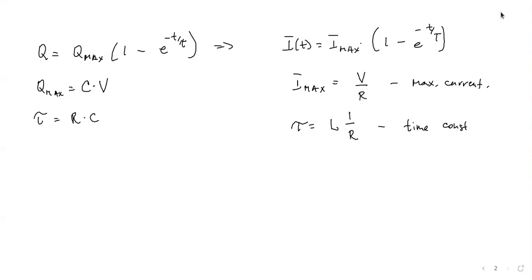The only probably difference between capacitance and inductance is that after a long time, the current through the capacitor is 0, but you have a certain charge. And inductance, after a long time, will change into a piece of wire because current will be constant. The inductance is not a piece of wire only if current is changing and you have back EMF. But if you wait long enough and all these transitional processes end, then it will be just a piece of wire because all your currents will be constant.